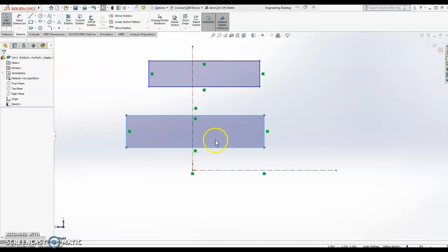So I've drawn my true rectangles. Now I need to have them on this line, because this is one of the center lines of my part. And in fact, I want them to be centered, because when I make it bigger, I want it to automatically stay at center. So how do I do that? Well, the book will put this X pattern, St. Andrew's cross, which you'd see on the Scotland flag, straight through here.